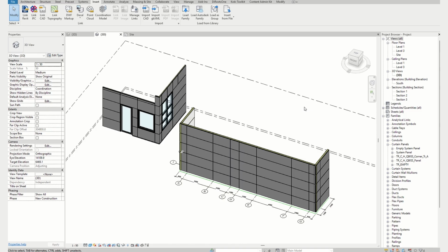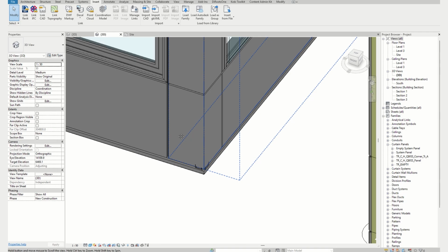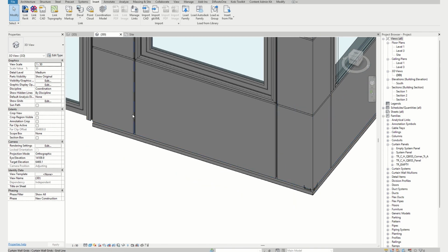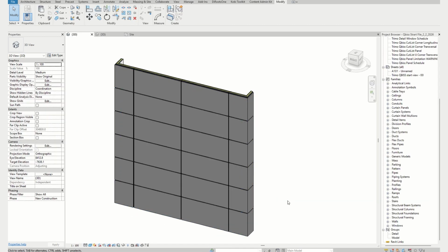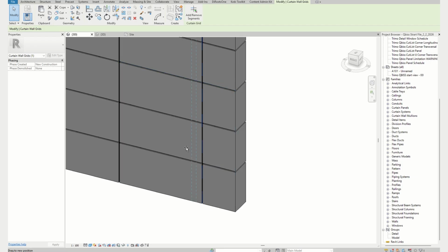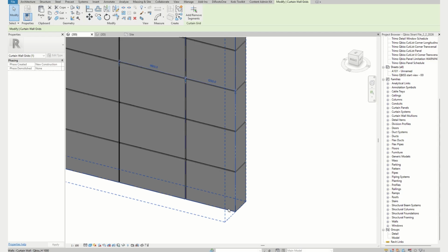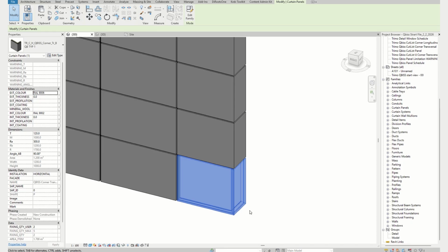How do we now add transversal prefabricated corner elements? Okay, a corner element is also a curtain wall panel family, very similar to the flat panel. Let's look closer at our sample wall. One side of the corner element is a part of the curtain wall and it is controlled with grids. The other side is a part of the neighboring facade and it is controlled manually.